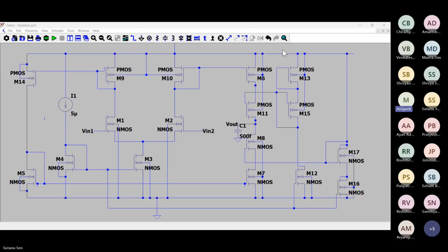So I have to slow down maybe, or use some pen and paper, or basically use drawing to explain. At least as far as the gain is concerned, he has already shown a big gain, and the only issue is that the input required DC difference is pretty significant, and bandwidth is low. Compensation has been done to get the phase margin required. Transient response is also coming. Whatever the AC response shows, the same transient response is also coming. So these things are done.